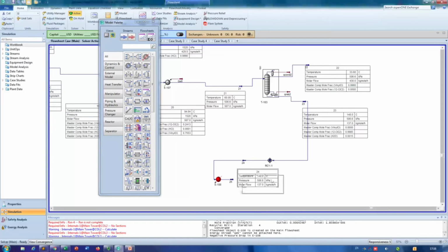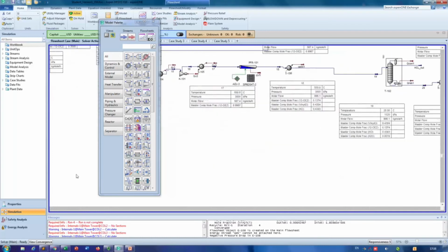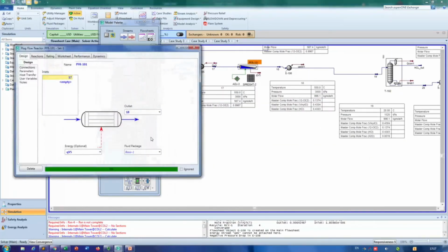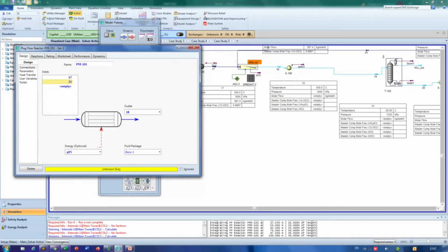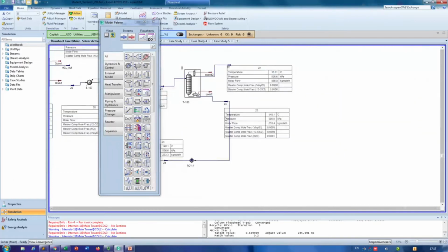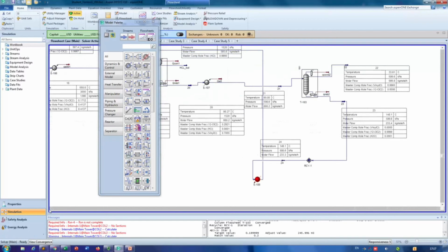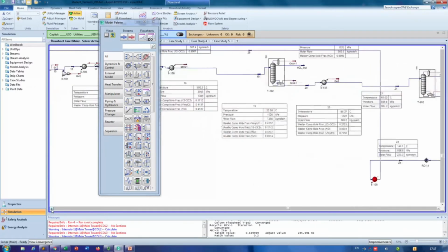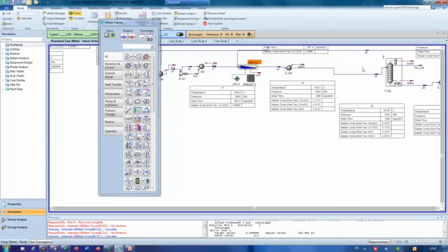148 so far. Good. Okay, this is 24. So stream pressure 25. So let's go to PFR, our pyrolysis chamber. Double click on this one, and then add our new stream, which is 25. It will solve anyway. Now you see everything is solved completely, because it will suddenly have this temperature shock from the recycle stream. Yeah, so now everything looks fine.